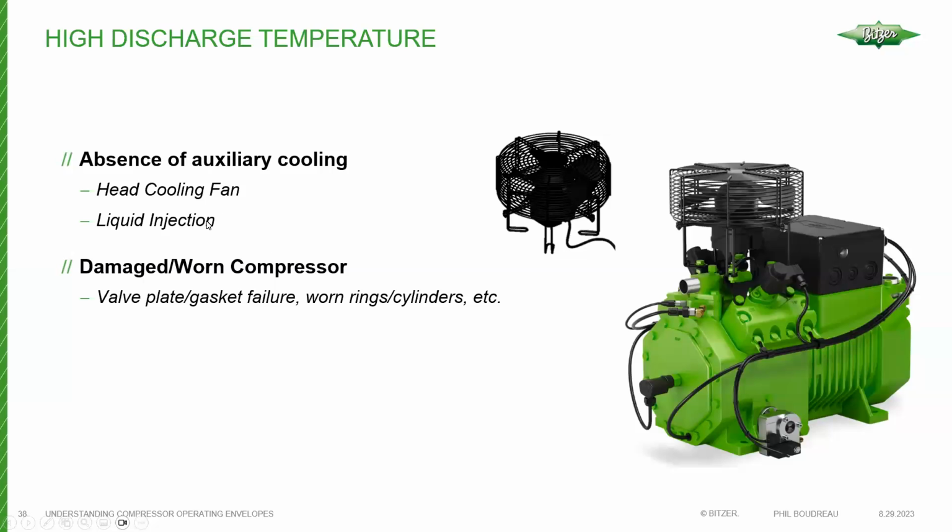Same thing with liquid injection. If something happens with the liquid injection, an orifice plugs up due to a dirty system or something like that, a discharge temperature sensor would take that. In the case of liquid injection, that will be the IQ module. Then the IQ module can safely take the compressor offline before it overheats too much and creates a problem for the compressor and also for the oil.